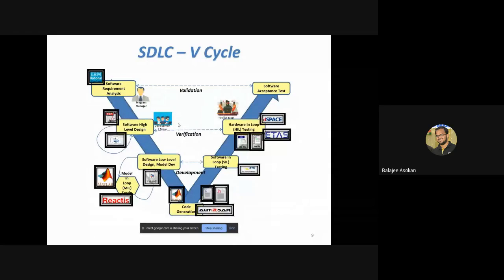Now you will have a prototype of a sensor fixed, which will give signal input to the ECU via this hardware setup. My ECU will process the algorithm, which is in the form of machine language in 0 and 1, and give the final output. That output will go to an actuator system, something like a breakout box, which will just flash a light and tell me.